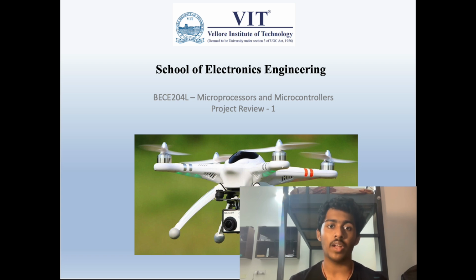Our objective with this flight computer was to integrate these sensors into a comprehensive real-time monitoring system. The system tracks key flight parameters like pitch, roll, yaw, pressure, temperature, altitude, and geographical position. All of this information is vital for ensuring the stability, safety, and accurate navigation of the vehicle during flight. For example, knowing the altitude and pressure can help you maintain a proper flight height, while the orientation data can help adjust the flight's tilt and direction.